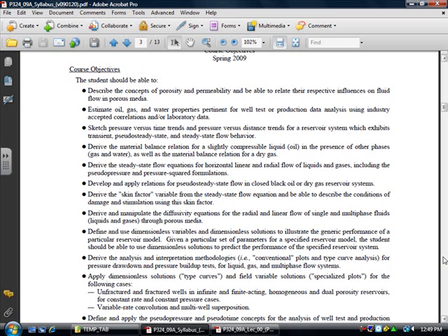The software allows you to believe that you can quantify non-ideality by changing the skin factor. Don't do that, or at least don't do it without going to the church or the mosque or something and looking for divine guidance. It is a tough, tough problem. The skin factor will have an effect in our vernacular as a constant pressure drop. It may not in fact be constant, but that's how we're going to think about it. So when we're looking at a particular pressure trend, the intercept will be corrupted, if that's what you want to think about it, by the skin factor.